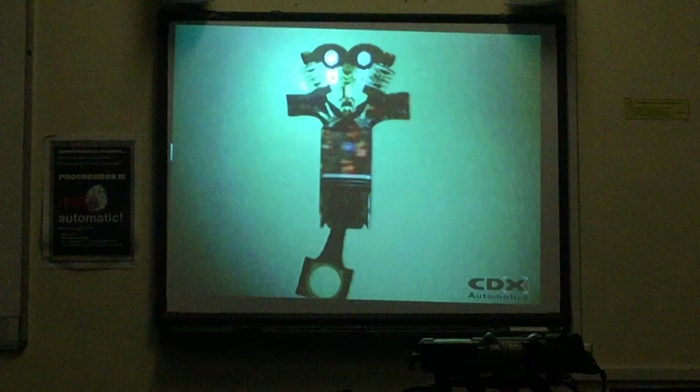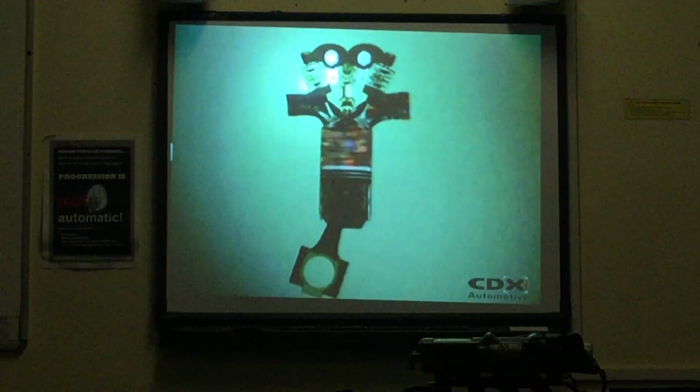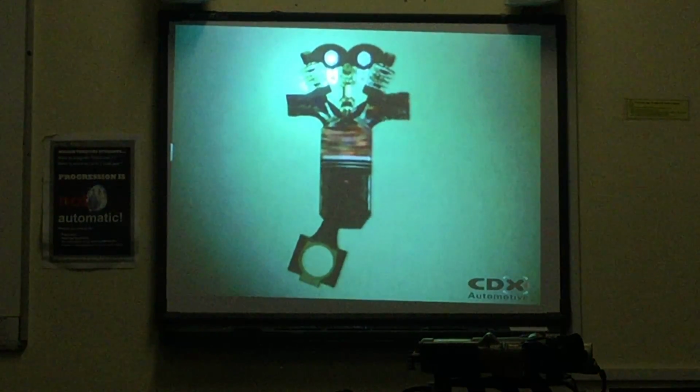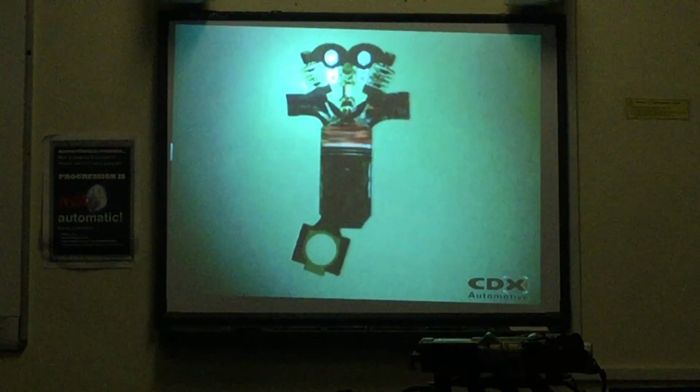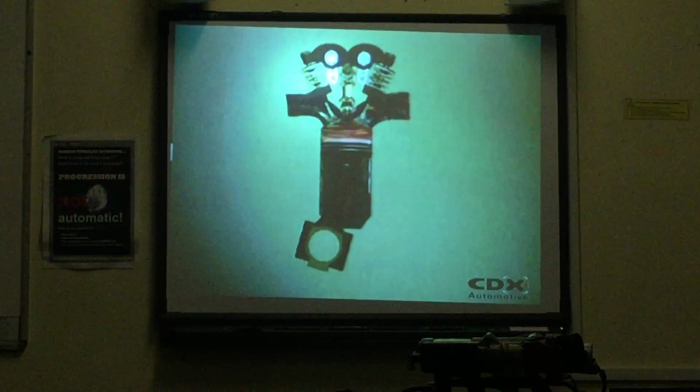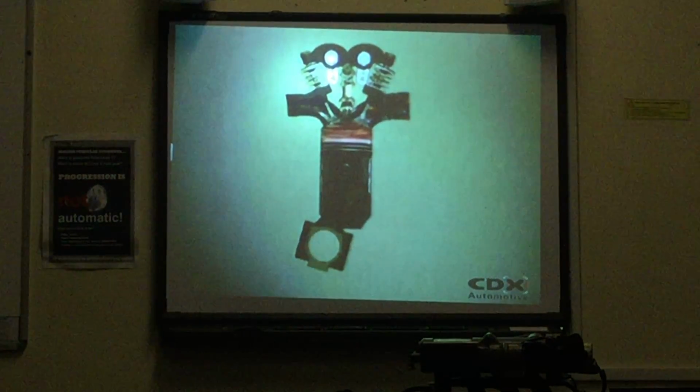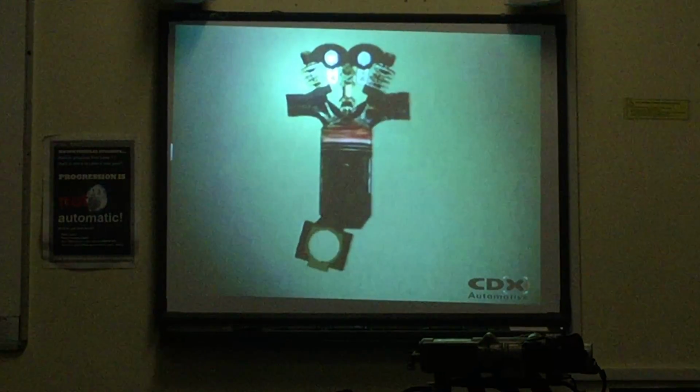The piston reaches bottom dead center, the inlet valve closes, and the intake stroke ends. Both valves stay closed as the piston leaves bottom dead center. The piston moves up, squeezing the air-fuel mixture into a smaller and smaller volume, which compresses it. That makes its temperature rise, and that makes combustion easier.